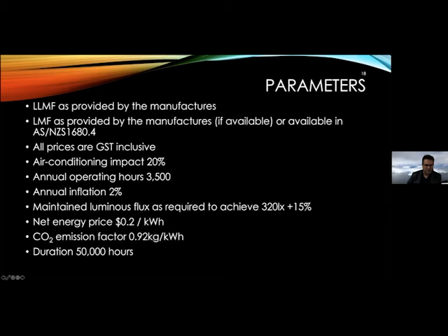My apologies, something happened. I base the operating hours on annual operating hours of 3.5 thousand, annual inflation 2%, and the maintained luminous flux required to achieve around 320 lux. We're talking about the indoor application.